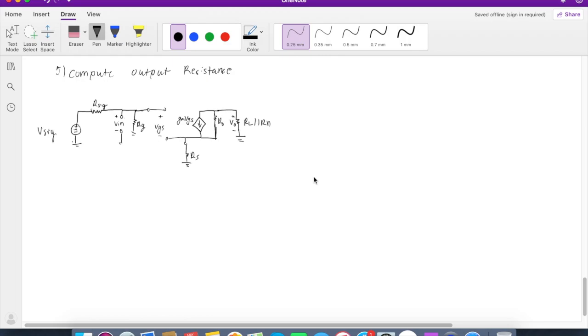And now finally the output resistance. So in the output resistance, as you might have seen in the transistor videos, we want to look at the place where the output terminal is. What's interesting is the original circuit actually looks like this: RD in parallel with RL, where only RL actually has the voltage output terminal, except they both do share the same voltage, but it does not mean the terminal is connected to both of them.